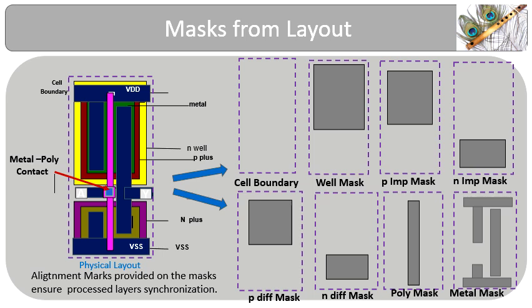During extraction, design rule checks, DRC, and layout versus schematic, LVS, verification are performed to ensure that the generated mask data matches both the physical constraints and the intended circuit function. Finally, the verified mask data is converted into a format suitable for photomask fabrication, where high-resolution mask plates are written using electron beam or laser writers. These photomasks are then used step by step in the lithography process during wafer fabrication.